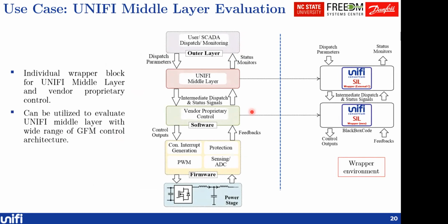This will receive the dispatch parameters from the SCADA layer and translate them through some intermediate dispatch signals to the vendor proprietary control layer, so that it can ensure that the inverter itself is fulfilling the UNIFI specification requirements.